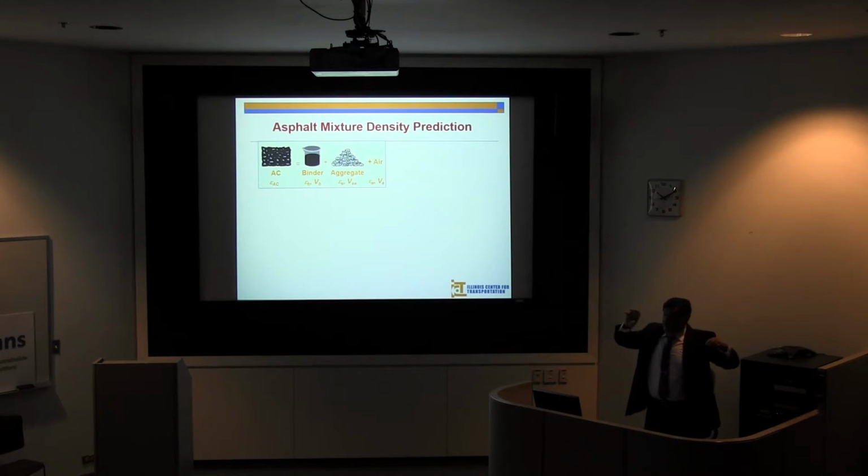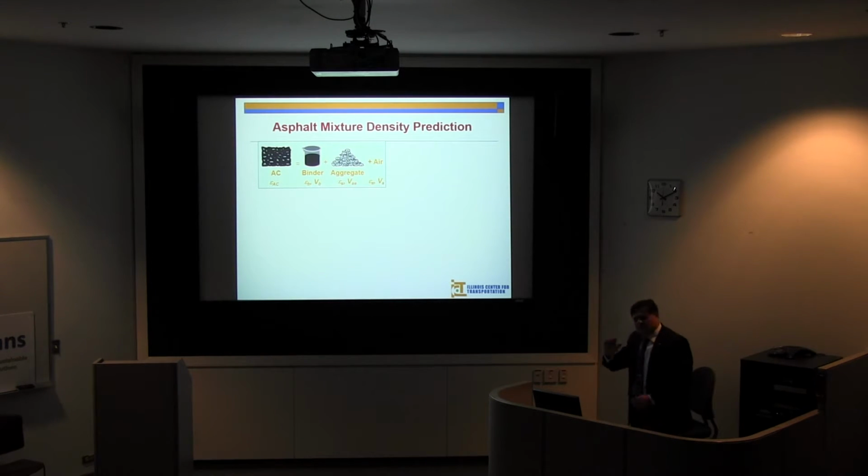So simply, if I have the dielectric constant of asphalt concrete and its volume, now the dielectric constant for each component, if it's like aggregate, asphalt, air void, and the portion of the volume of these three materials, from this I can know what's the dielectric constant of the asphalt concrete. So keep this in mind here.